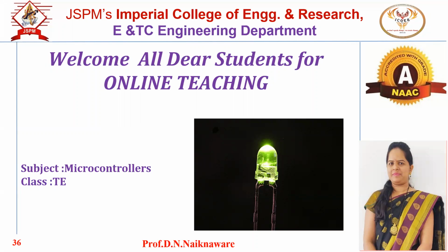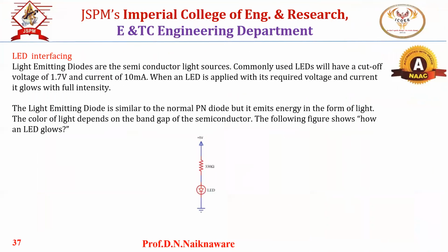then we have to stay at that position for some time, and after that we have to turn off that LED again. So in between on and off we have to provide some delay so that we can analyze or observe the blinking of the LED. Now I am going to show you the LED interfacing using Proteus, again a simulation software. So let's see.